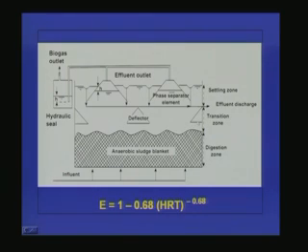So here we can see this one, this is nothing but a deflector beam, and we have another arrangement like this. So all these things together are known as GLSS, that means gas, liquid, solid separation system. Here, all three components, that means the liquid, the biomass as well as the biogas, will be coming up in this direction, and we want to separate all the components separately. That means we want to have liquid separately, solid separately, and gas separately. So that is what is taking place in this zone.